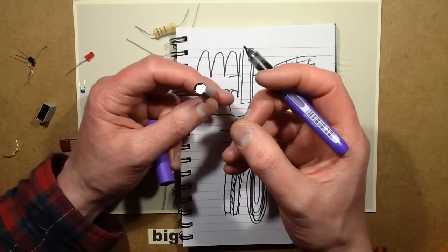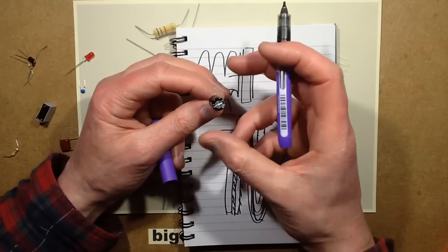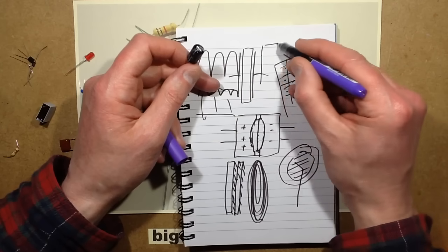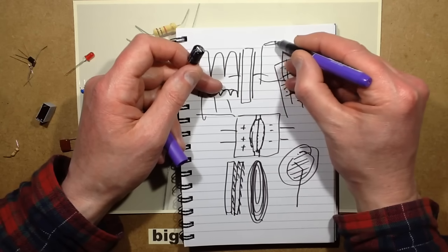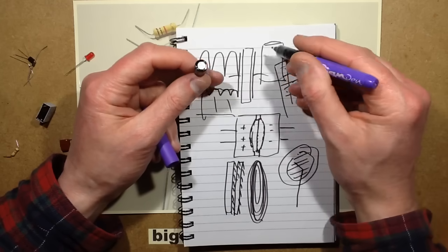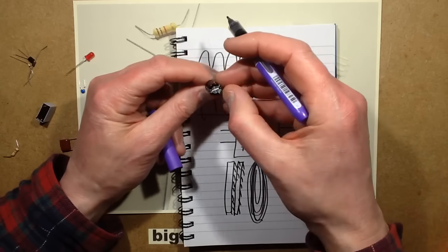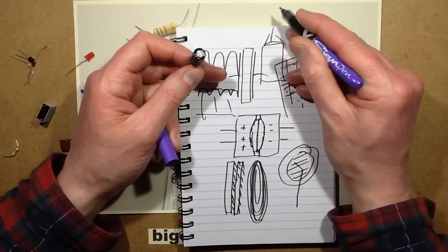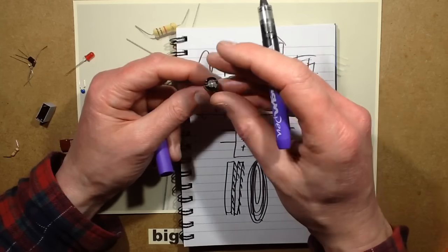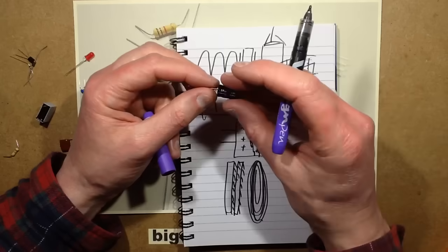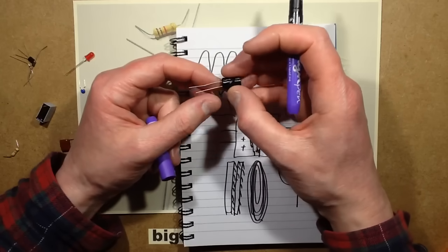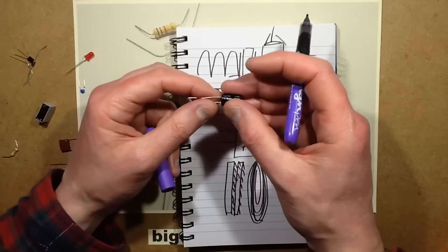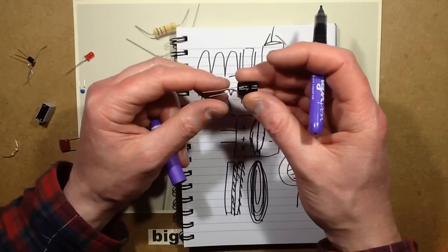Basically it turns into sort of a resistor, and it boils the electrolyte. And when that happens, if you looked at it from the side, the top would bulge up. But if it goes too far, that X that's etched onto the top will split open and it will vent out the top. And the other option, if it doesn't do that, is sometimes it blows the whole can off and it just makes a mess. It gives out a vapour of the electrolyte, which is slightly caustic.